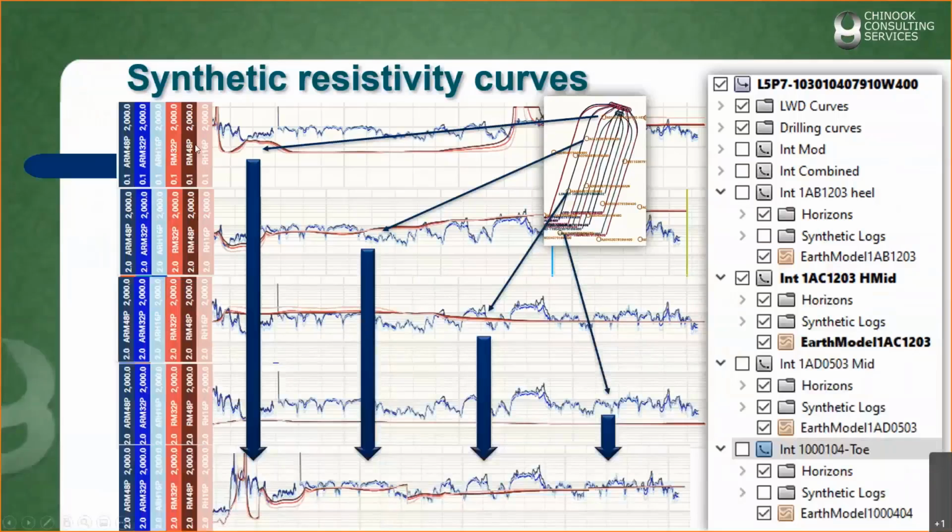And this is how it would look. What we have here is different simulated resistivities based on different Earth models. For each individual stretch of the producer, or an infill well for that matter, for the wells that we analyze, we do separate interpretations with corresponding Earth models, just like we would with a single Earth model, but now we do it 4 times over in this example. This model is then stitched together, and the resulting simulated resistivity curves reflect the profile chosen in distinct areas of the wellbore from that combined Earth model that we've seen before.